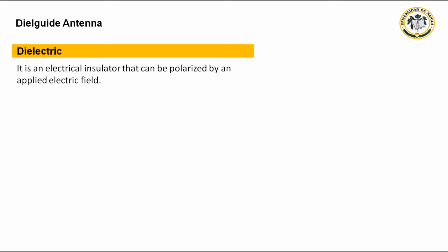Dielectrics are insulating materials, or very poor conductors of electric current. When dielectrics are placed in an electric field, practically no current flows in them because, unlike metals, they have no loosely bound or free electrons that may drift through the material. Instead, electric polarization occurs. The positive charges within the dielectric are displaced minutely in the direction of the electric field, and the negative charges are displaced minutely in the direction opposite to the electric field. This slight separation of charge, or polarization, reduces the electric field within the dielectric.